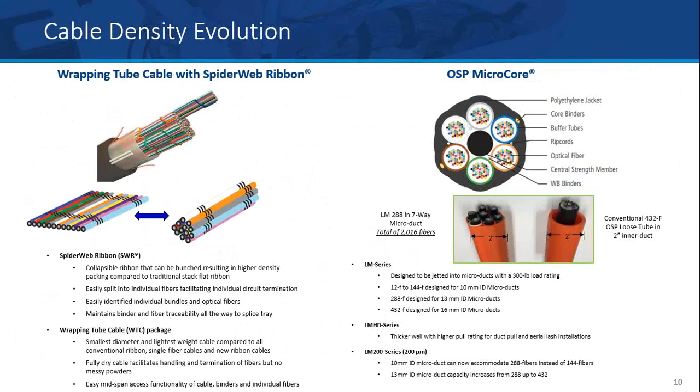They've been able to shrink the 200 micron fiber down. So now you can imagine you get the fiber size down, allows you to get smaller buffer tubes again. Smaller overall cable, so that really accelerates how much you can put into a duct. So taking the example of that 13 millimeter duct where we were putting in 288 fibers, you're actually able to then bump it up to 432 fibers for each one of those pathways. So it really gives you a lot of advantage there.